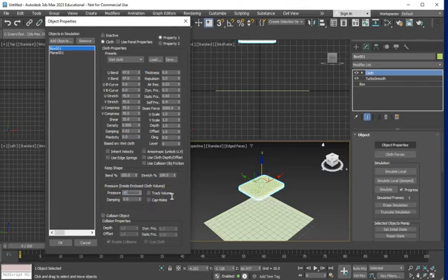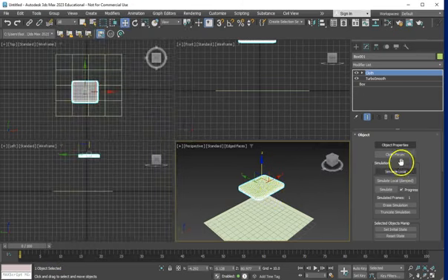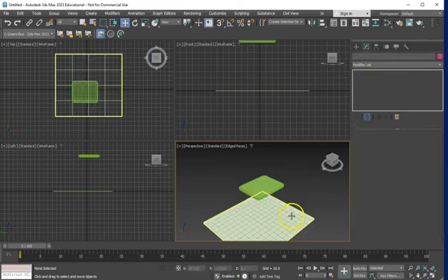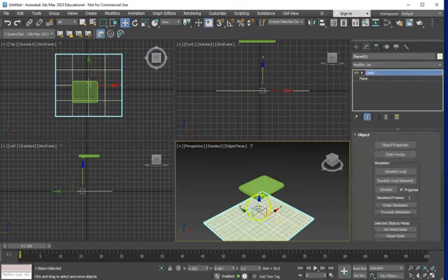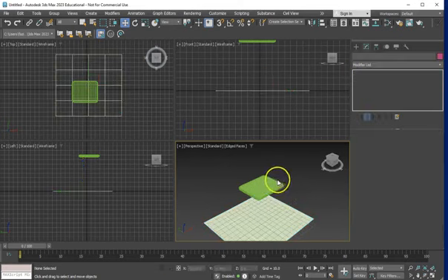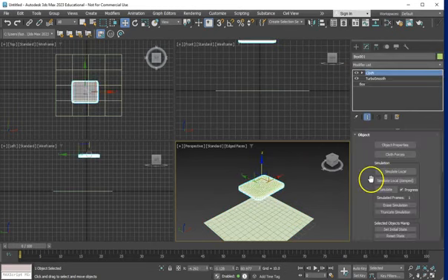So I will put 40 to pressure and 10 to damping. And this is our cloth. This is the collision object, and I click OK. So when I click this object again, you see that it has a cloth modifier. And because we put this object as a collision object in our scene, it has also the cloth modifier on it too.